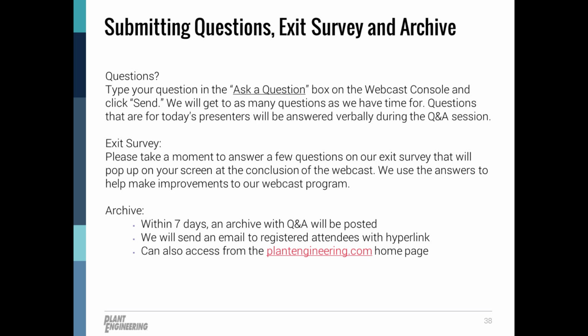Well, thanks, Michael. Ronnie, a question for you. What are the best practices for motor greasing intervals? Yes, another good question. I would say that this will depend on the run hours of the motor, and also the speed of the motor and the type of grease being used can all play a key factor. But just remember that a big part is the run hours of the motor, not necessarily to grease all your motors at the same time on a schedule. It's not unusual at all for different motors in your plant to be on different greasing intervals due to the run hours or the speed of the motor.